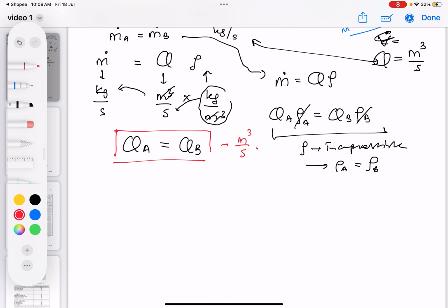And then, I also know that flow rate is equal to meter cubed per second. And then I have a velocity because it was moving. Therefore, I have velocity in meters per second. You will notice that these two can be related, because this one on the left side is meter cubed and this one is meter. So I simply multiply by meter to the power of 2, and I end up with meter to the power of 3 per second. Meter to the power of 2 is the unit for the area.